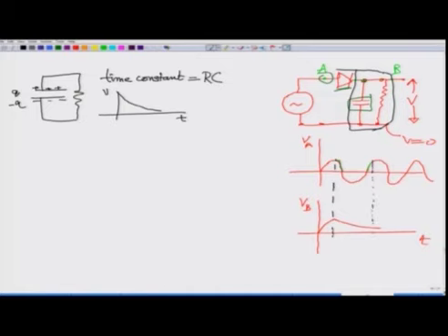In this drawing it is not like that, but suppose it is equal. I can draw another curve. So, the capacitor voltage was decreasing, at this time they have become equal, and after that the voltage on the A side, the voltage here, is now increased further, the diode becomes forward biased.